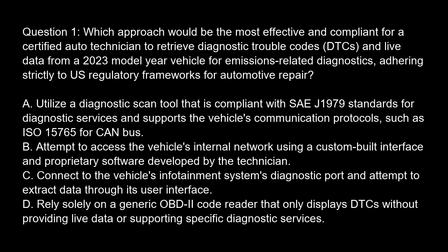Option A. Utilize a diagnostic scan tool that is compliant with SAE J1979 standards for diagnostic services and supports the vehicle's communication protocols, such as ISO 15765 for CAN bus. Option B.